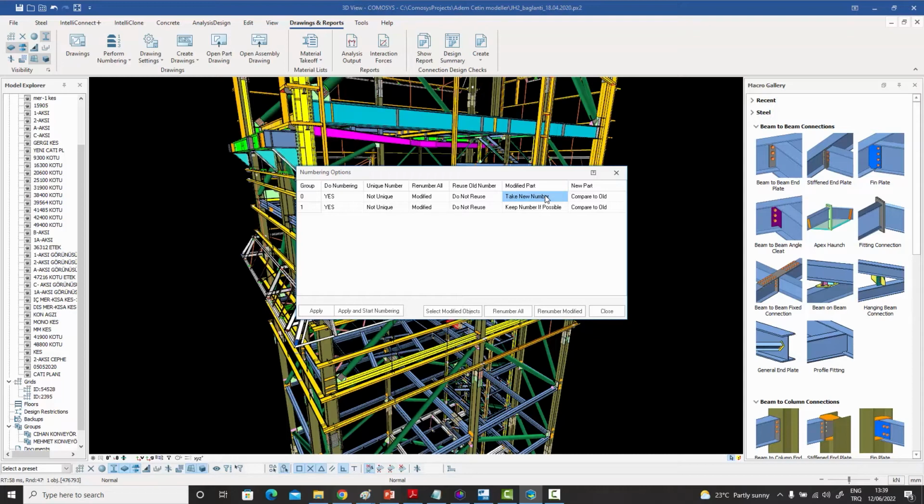You don't want to say, I had this part called part 7 and there were 7 of those, but now I made some modifications and now there are 13 of those, because this can confuse the shop sometimes. So it's common practice in those cases to say, even if it starts to resemble an earlier part, you give it a new number despite that.